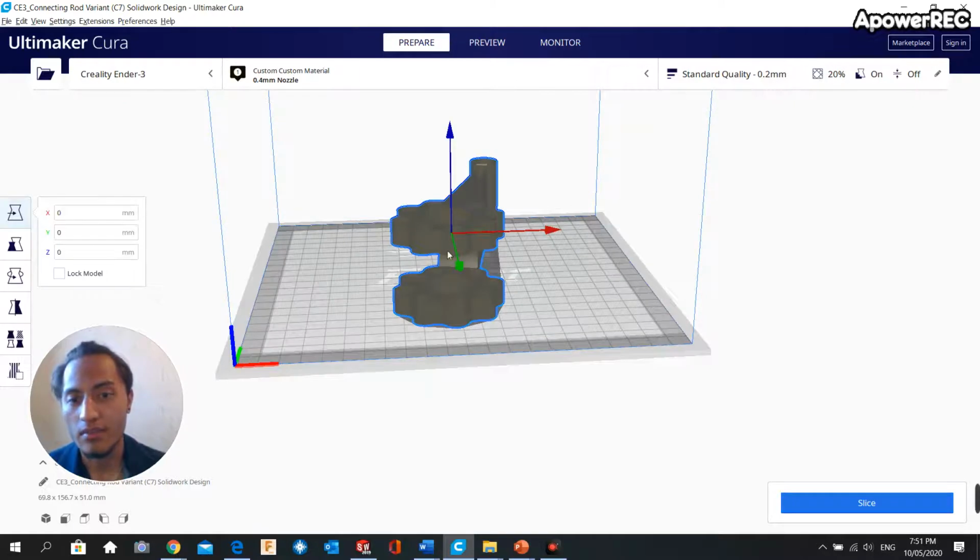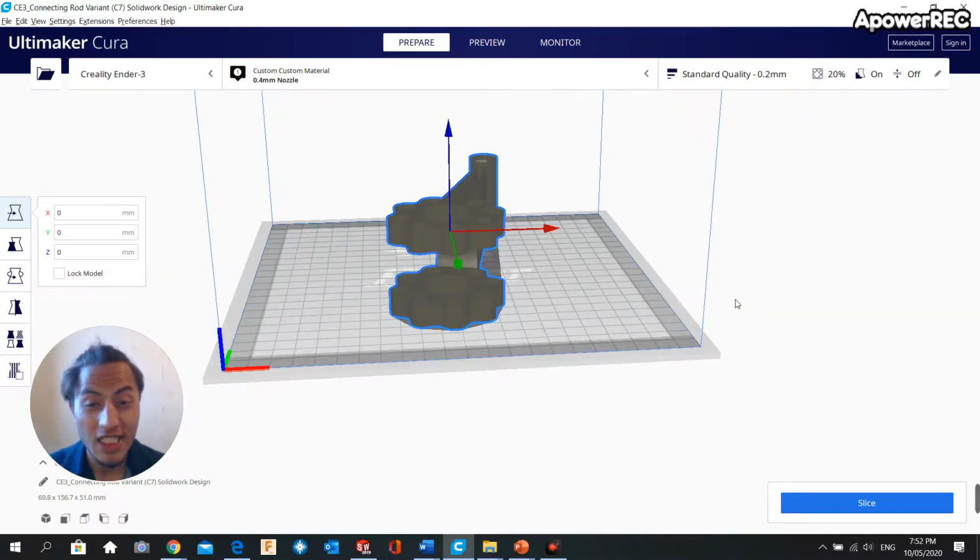And obviously make sure when you load it in the base of the Cura software, XYZ is 0. If it's not, then you print at the bottom as well, so make sure that it's 0. Also make sure the material is placed as trim and as efficient for printing as possible. If not, then there will be issues in printing. So all of that being said, that's how